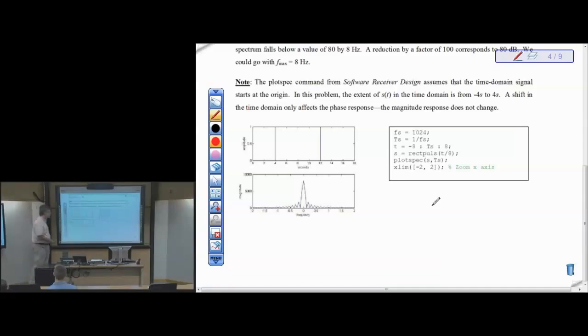So here's the first problem, which we kind of know in closed form. It's a sinc, and this point is always at half the sampling rate. So if you double the sampling rate, the shape will get smaller visually, but the actual frequency of the zero crossings doesn't change when you inspect that. And this point over here is minus half Fs.